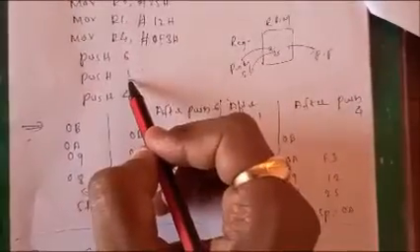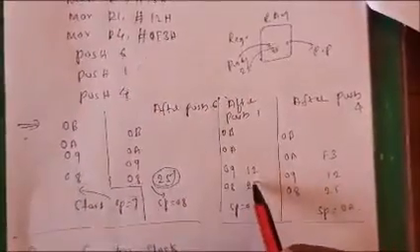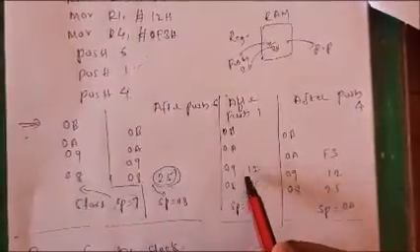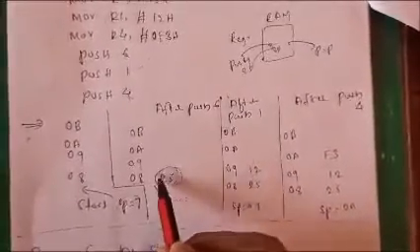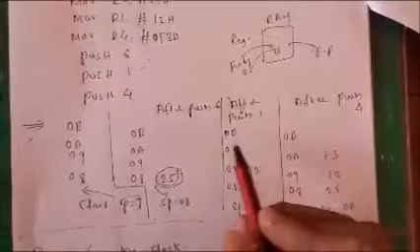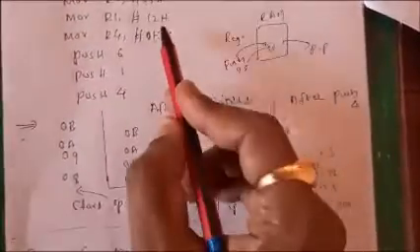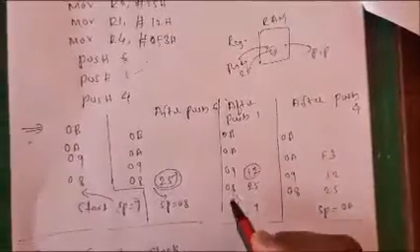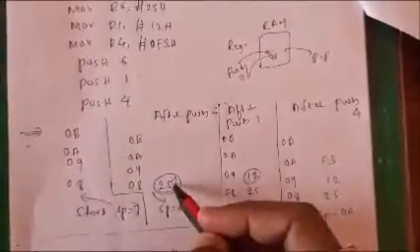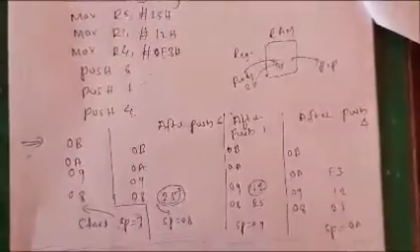Next, when you perform push 1, push 1 means R1. What is the R1 content? 12. So again it is going to be stored in the RAM location 9. Why 9? Because 08 is already occupied by 25. So when you perform the next push operation after push 6, this 12 is going to be stored as the second value. What is happening here? When you are pushing, the content increases toward the top side. That you need to observe.